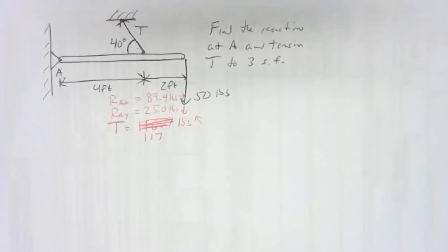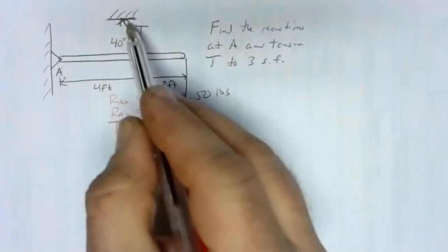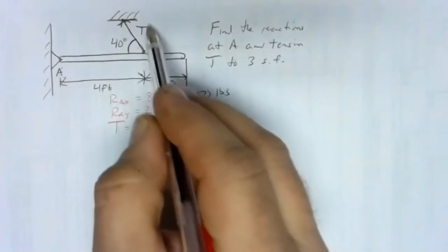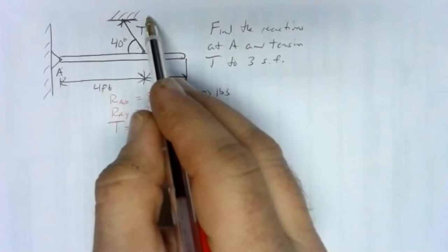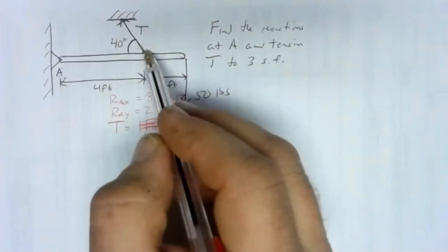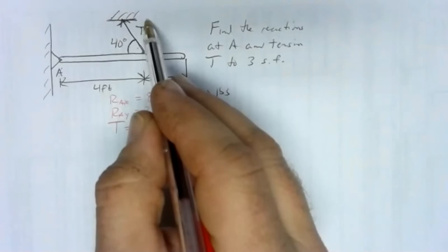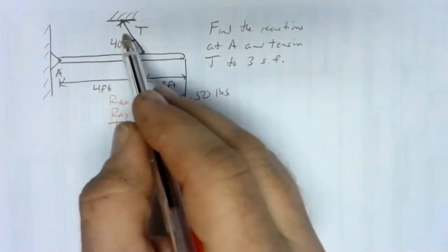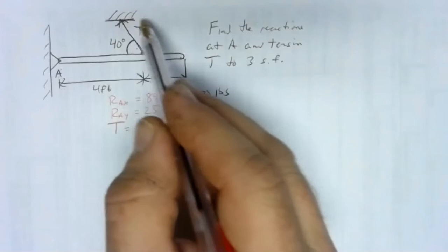The difference here is some trig's going to come in because now we're holding this tension off to an angle. There's the vertical piece of that. It's what's got to do the job that the vertical rope did in the previous problem. So one way to look at this is to think, well, the vertical piece of this force, the tension now, has to be high enough so that the vertical piece is providing the force that the previous rope did. So it's got to be 75 pounds pulling up. So being at a 40-degree angle, to get 75 pounds pulling up, you're going to need a higher tension.